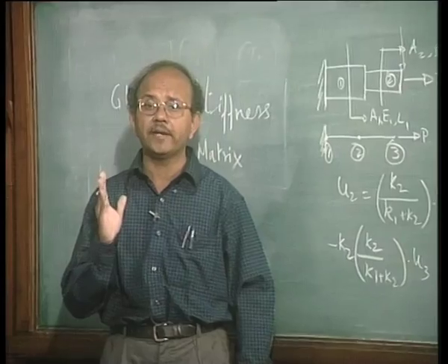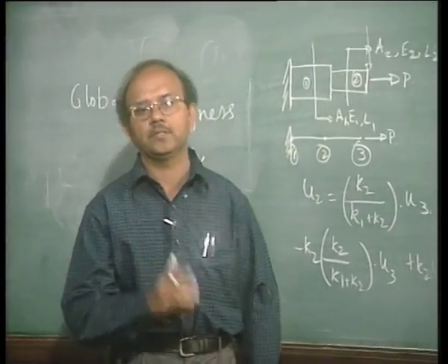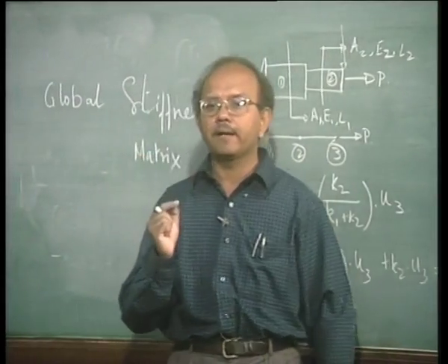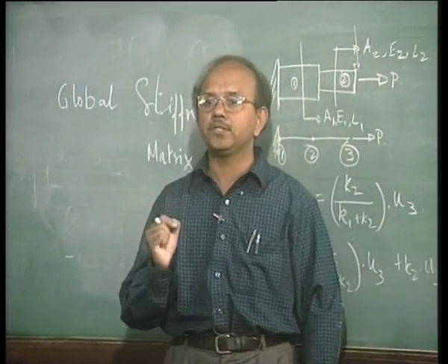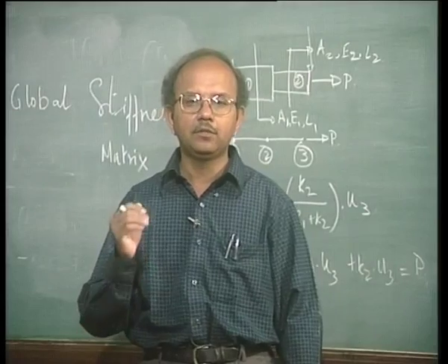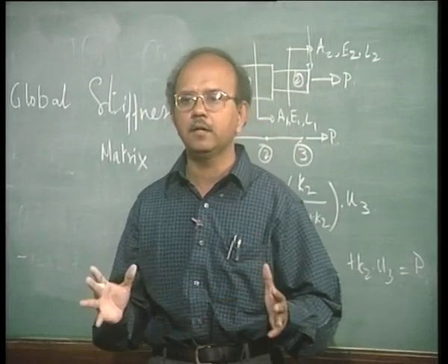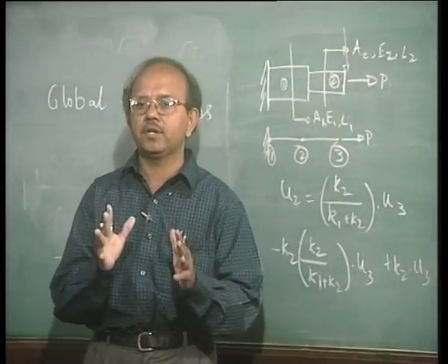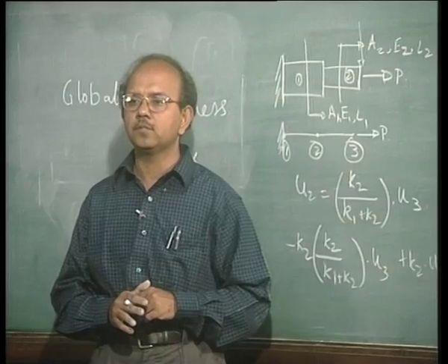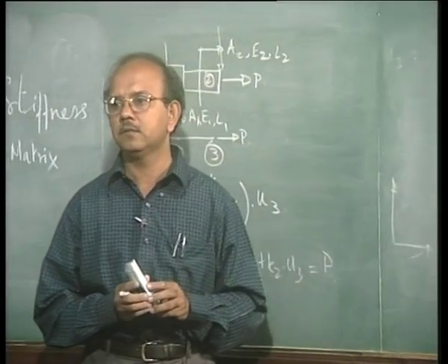So what is the result you are going to get from finite element? The result that you get from this finite element analysis is displacements. You don't get stress, please note, you get displacements. Then you go back and through the strain displacement relationship, you find the strain, and then through the stress strain relationship you determine stress. Is that clear? So this in a nutshell completes all the steps that are required in order to solve this problem. Any questions?